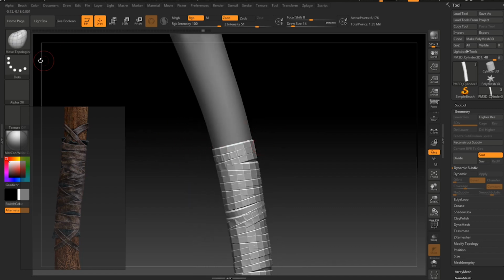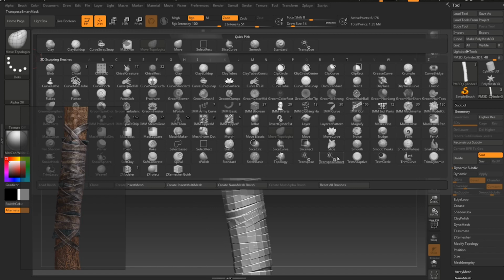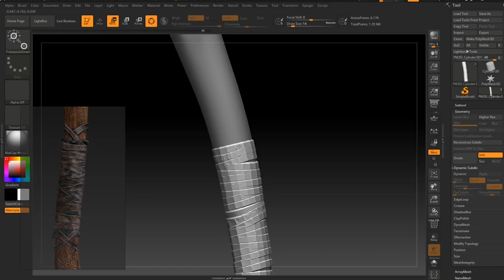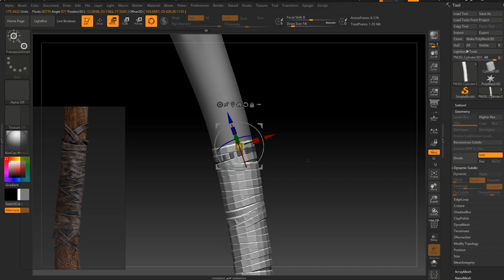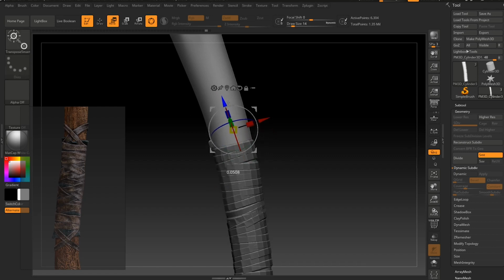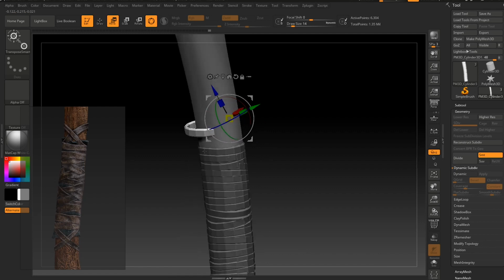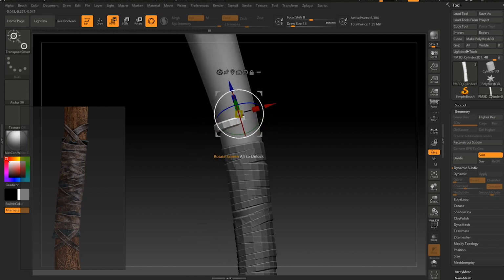Or you may want to go to transpose smart, keep control pressed, and then just drag, and you will select one of these, and then control click to invert selection, and now keeping control pressed, you drag out and you just took yourself a ring out of that equation, and you can now edit it, and it's part of the mesh itself, the ring mesh.